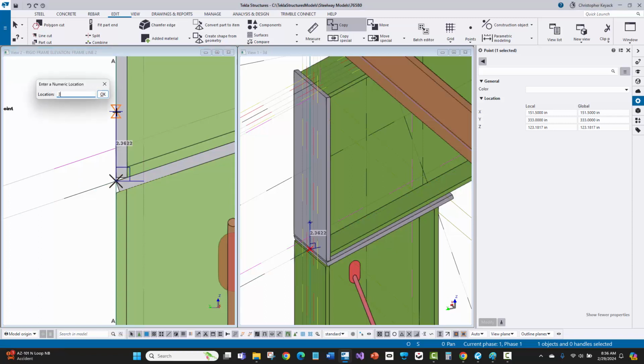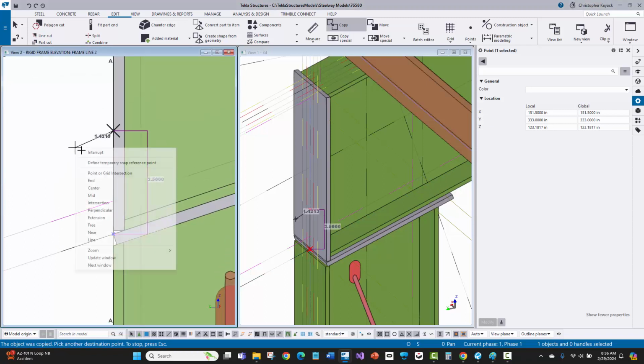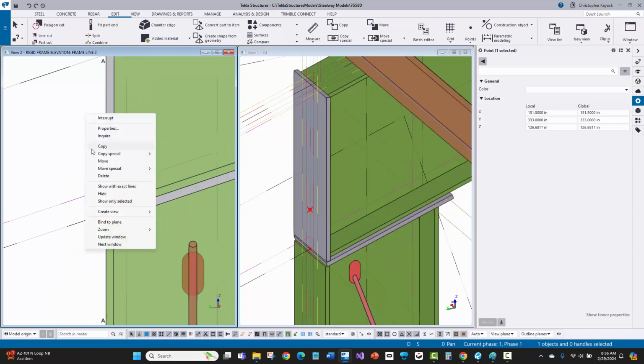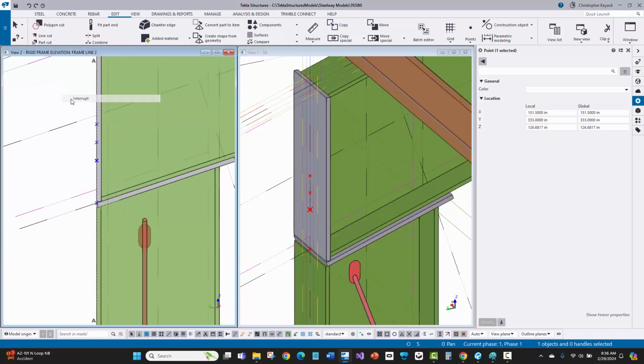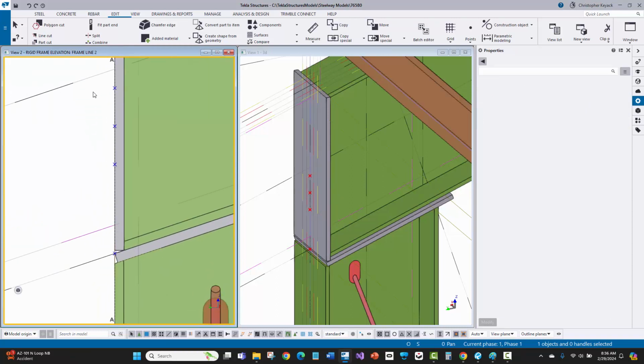So here I'll do 3.5 because it shows a 7-inch spacing on the center bolts here. And then I can even just copy this again, and I'll do, let's see, looks like there's 3 inches on the next one, and then 1.5 for the edge distance. So let's see, do I got that there? Yep. So I got, let me undo that. Let's see, what did I get?